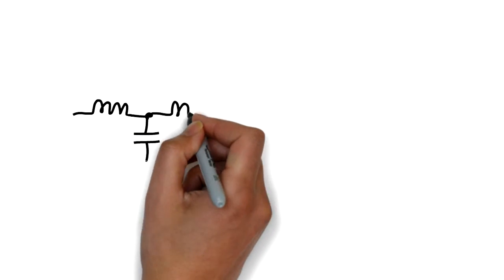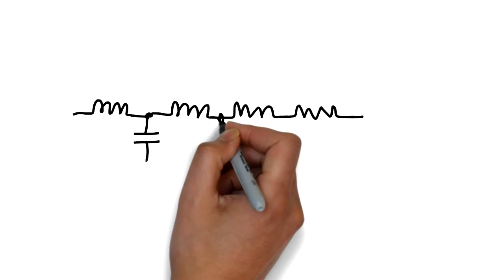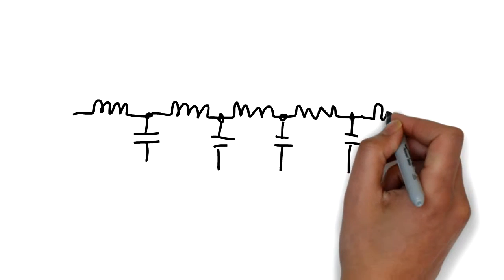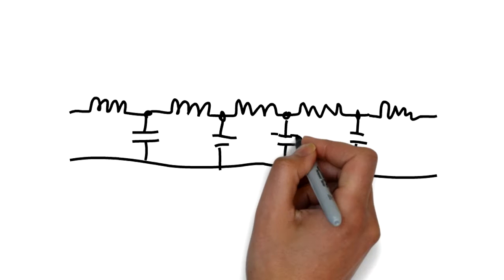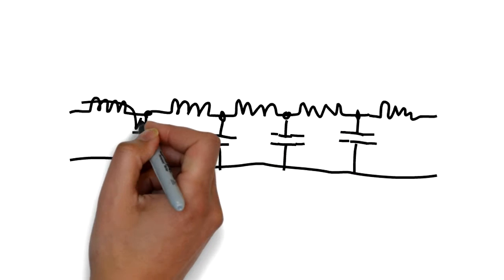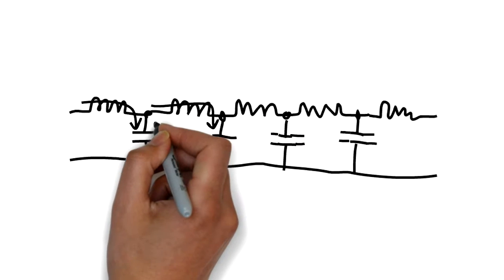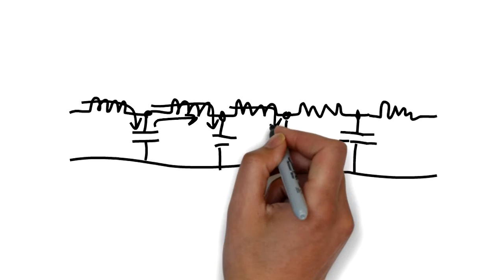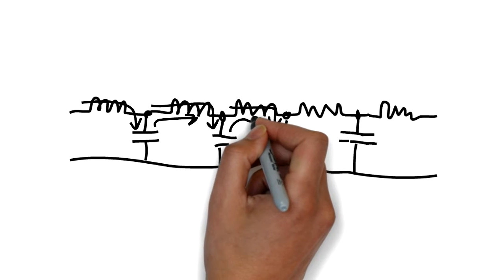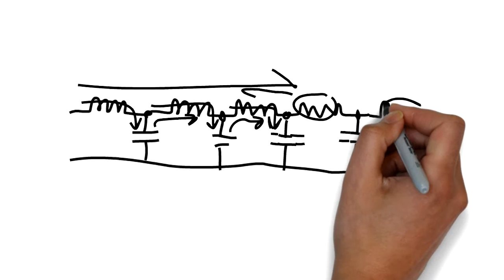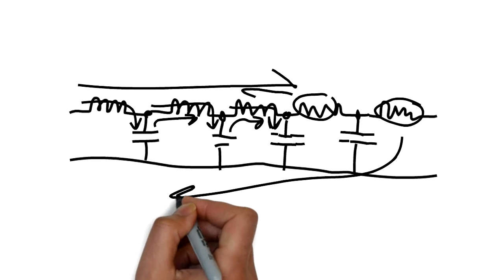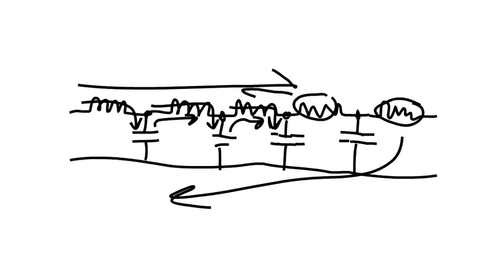Remember that the capacitive elements and inductive elements work together to propagate the signal forward down the line. And this is critical. If the capacitive elements, which we can think of as voltage buckets, change size at some point along the line, then the buckets will be underfilled or overfilled, and this will upset the critical balance. This will result in some of the signal being unable to continue propagating forward, and it will be forced to turn back. A similar issue occurs if the inductive elements change at some point in the line. The resultant change in current momentum upsets the balance, and some of the signal will flow backwards down the line to the signal source. So it's critical that we maintain a consistent transmission line.